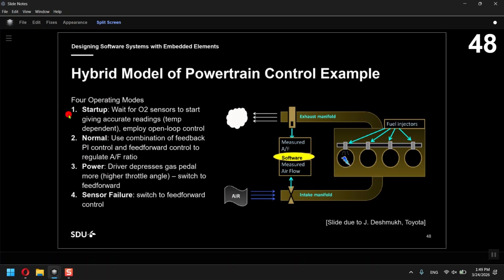However, in the case of fire, it doesn't matter what condition or state the fan is in, it should continue blowing air. This is very interesting for different reasons. In normal operation, when the temperature exceeds limits, you should shut down the system. However, in a fire event, you are not sensitive to temperatures. So you should run to death.